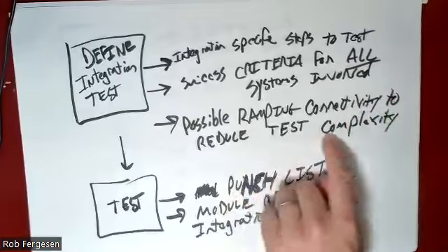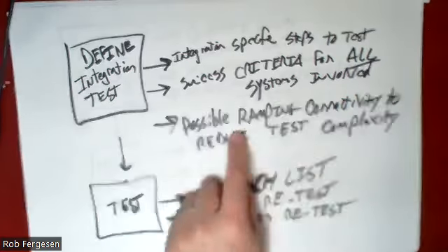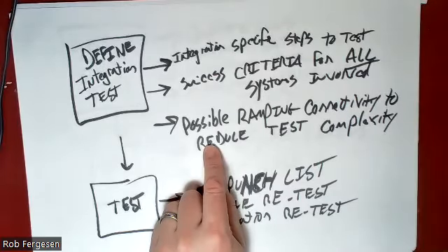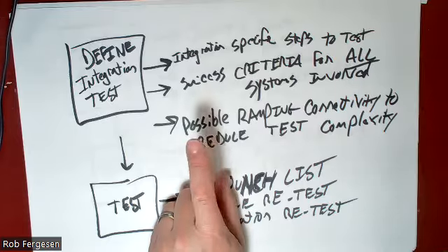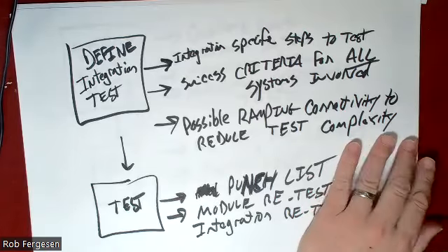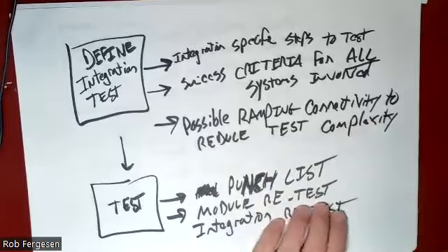This is a really good method of testing, especially if you have a whole bunch of modules that all hook together on, say, Wi-Fi or Ethernet, in which case they may interfere with each other. If you try to test them all at the same time, all hooked up at once, you may not figure out which module you're adding is causing the problem. So by breaking the testing down into one module at a time, one integration point at a time, and ramping up, adding them one at a time, you reduce your test complexity and confusion.